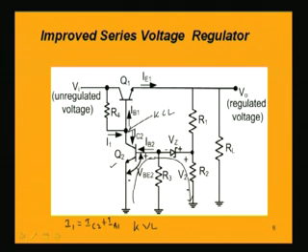That means we are getting a lesser base current IB1. Lesser base current IB1 means in the transistor Q1 the emitter current I1 flowing is also lesser. So finally the load current which flows through the resistance RL will be less. So V0 will now be less. So the effect of increase of V0 will finally be decreasing V0. That means it will be maintained at the constant value.